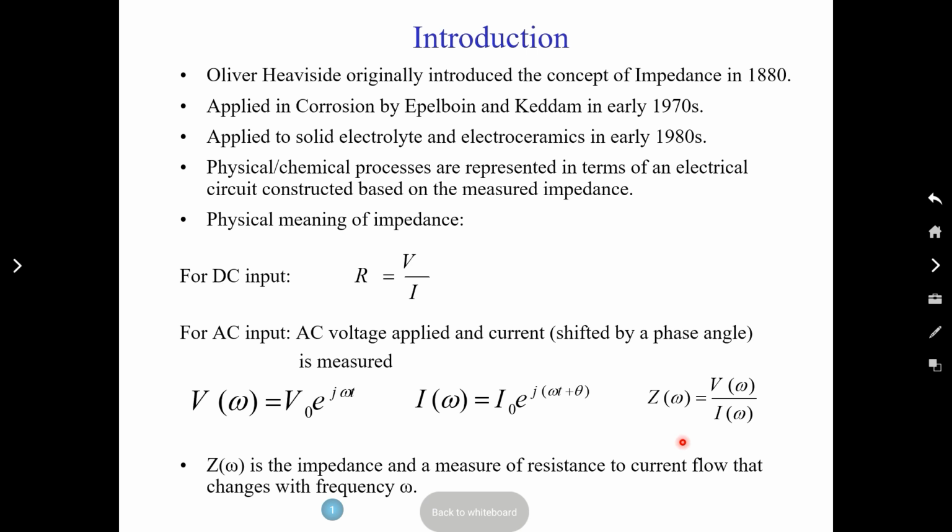So you have frequencies, real impedance, imaginary impedance. If we give you that data, the data is given to you from a previous sample. You take the data and then start doing the equivalent circuit modeling, and you'll get the answer.